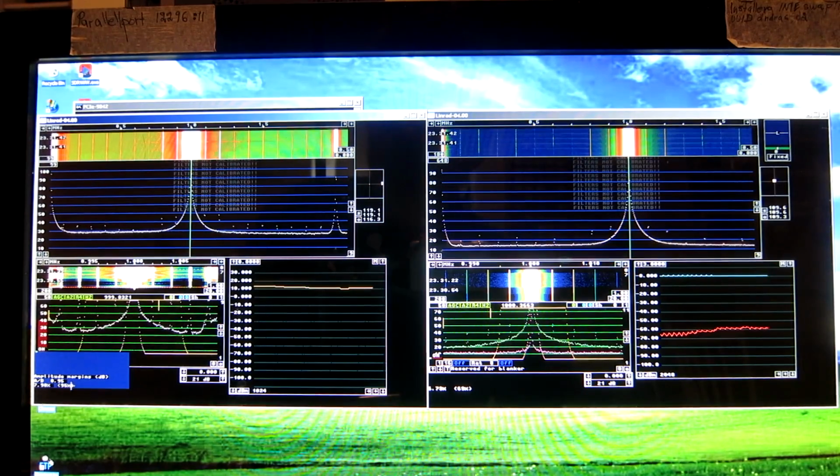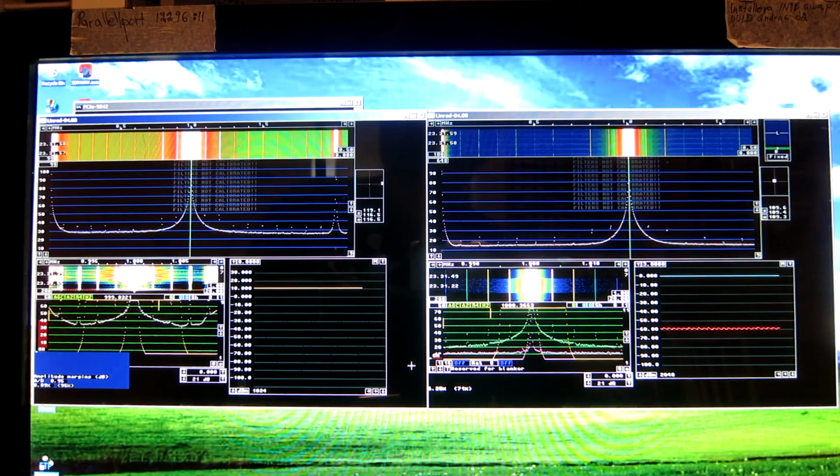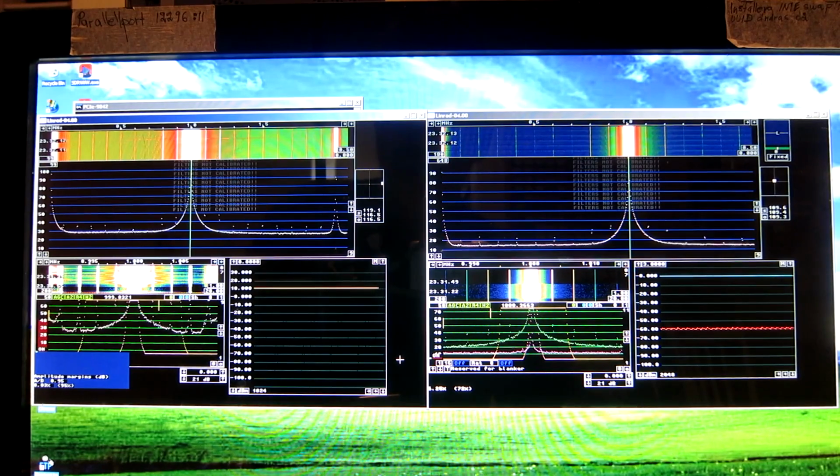Now I am 1 dB below saturation. The level on the signal generator is 12 dBm. Means the dynamic range is 12 dB plus the difference in noise floor, maybe 13 or 14 decibels. That's the difference between the bladeRF 12 bits at 40 megahertz and the PCIe 9842 with 14 bits at 200 megahertz, which corresponds to 15 bits at 50 megahertz.